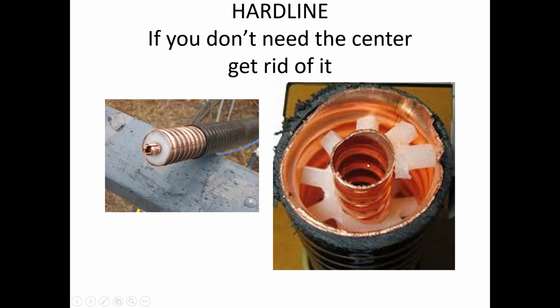Now, if you don't need the center, then why not eliminate it? And that is the case in many instances. This is called heliax cable. There's no center. There is a center conductor, but this is it, because that's where the electrons are going to be. Nothing is going to be here. It's called heliax because of this construction going through the whole cable, and this area will all be filled with some gas. Here is something called hard line, which you may be more familiar with. It's totally surrounded by copper. Here's your insulator, your dielectric material, and again, no center, no reason for it.